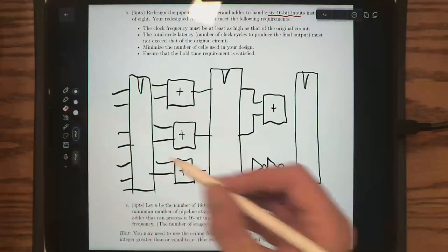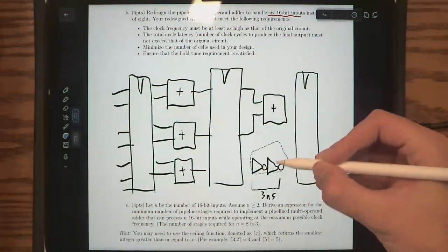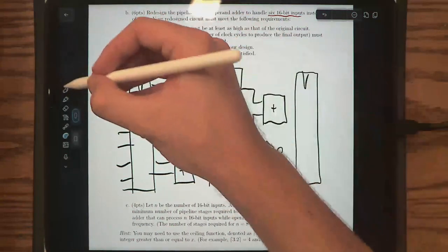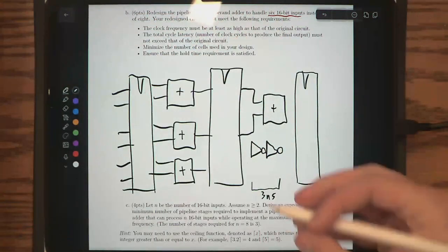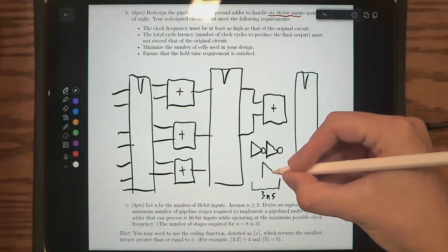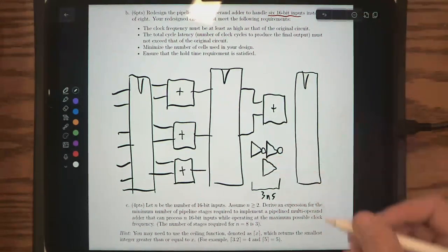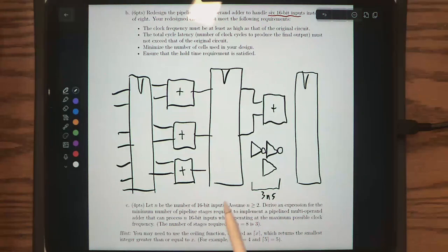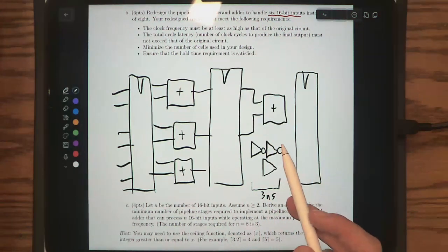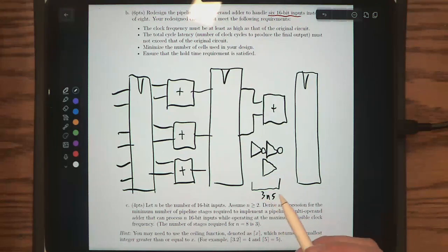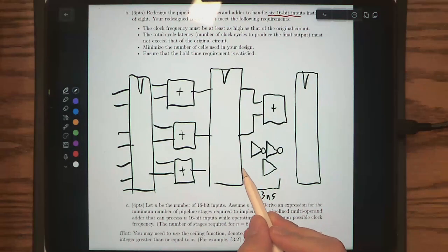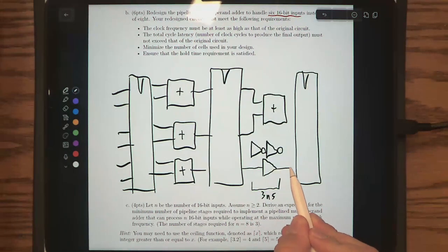You can also, if you want, just not put the little circle right there. The circle is the thing that denotes that there is an inversion happening. So you could also just put a triangle right here. This is also a reasonable symbol for a buffer. So both of these symbols are the exact same, and both of them are 3 nanoseconds, and they're both just 2 inverters, one right after another. Okay, so this is the inverter. This is the buffer. So sure, we can put that there.